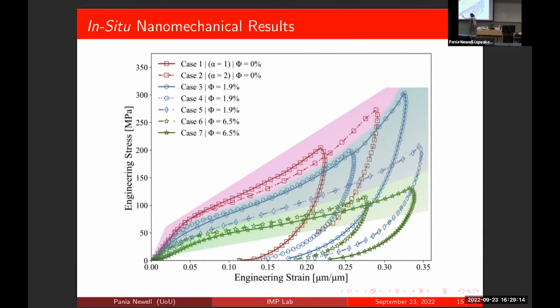And if you follow the linear elastic region, just focusing on only the elastic properties, we see there is a degradation, which is obviously a function of the porosity. This is a known factor at the macroscopic level, but at the nanoscale, to my knowledge, this is the first time that a porous structure is being tested at the nanoscale, or higher, a couple of hundred nanometers long. And then there's the behavior of the softening and the unloading. Those are other stories that also reveal the pore dependency.